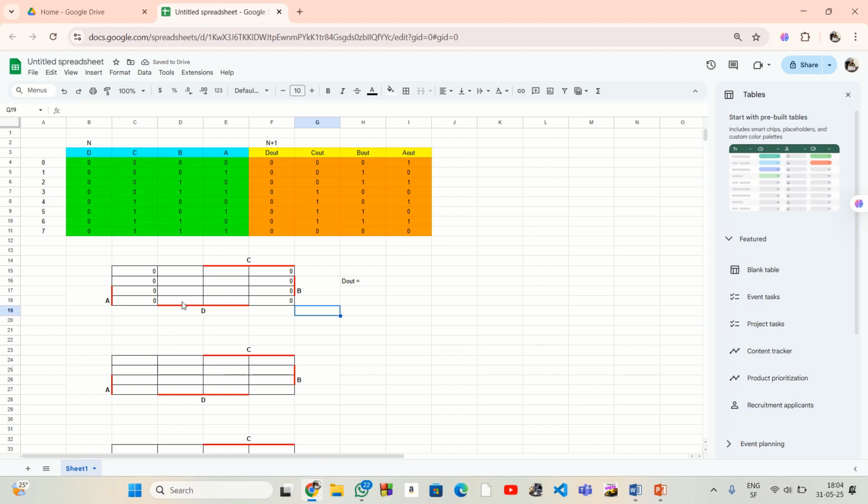values because I am not interested in any number that is greater than 7 because my counter is supposed to be counting from 0 to 7, bearing the fact that it's working in 3 bits. So it means this part will be x, x, x, x, and also here will be x, x, x, x, and that's how it looks. So just to align everything at the center, I'll highlight that and come to my justification and align them at the center like that.